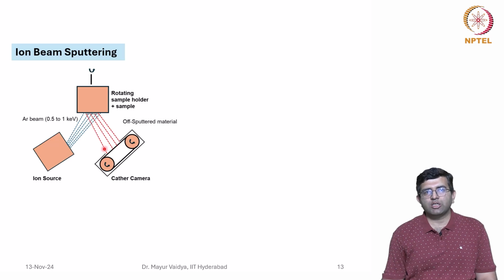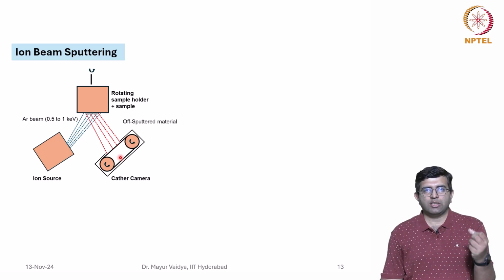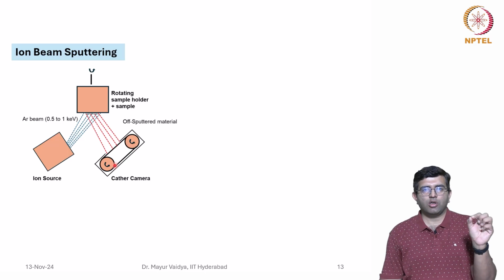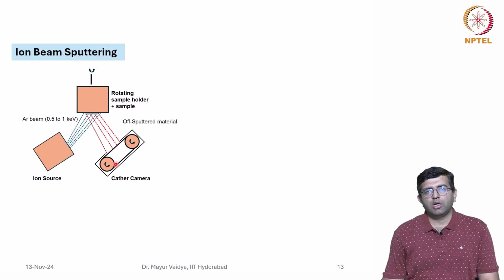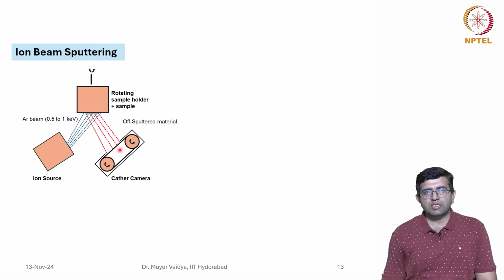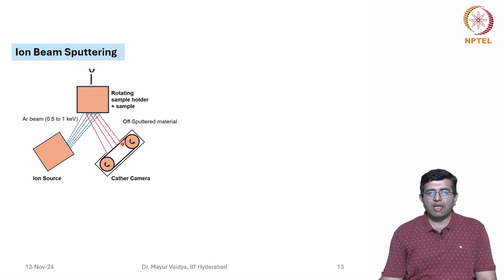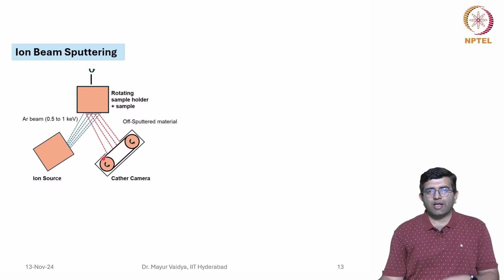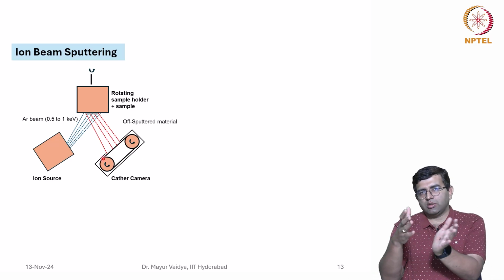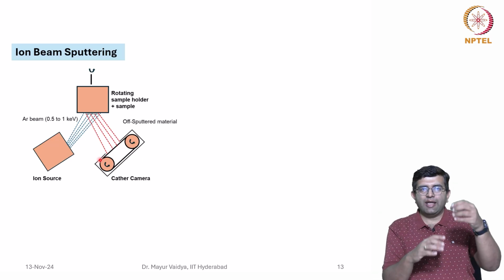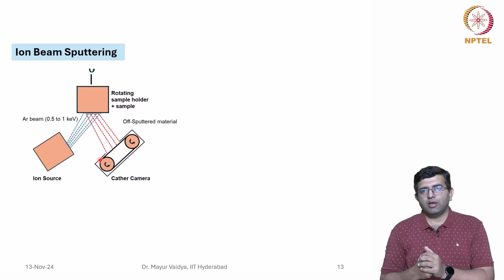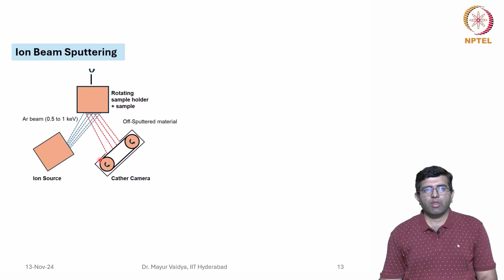You measure the sputtered layers. You can control the voltage and the current, so you can control how much thickness of material is removed. The sputtered layer thicknesses can be in the range of nanometers. You can collect several such layers, 20, 30, 40, and then measure the radioactive counts.